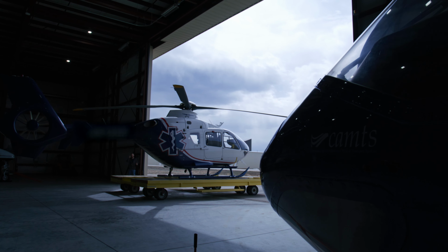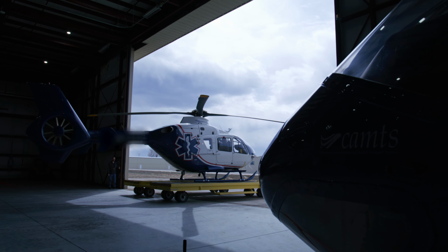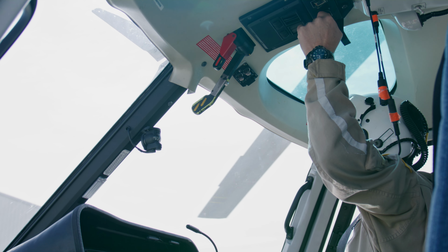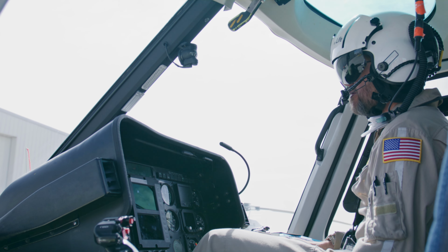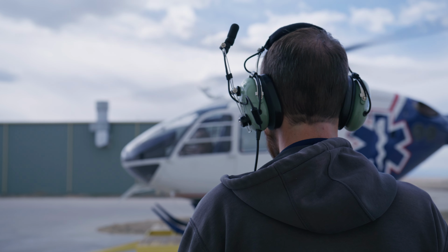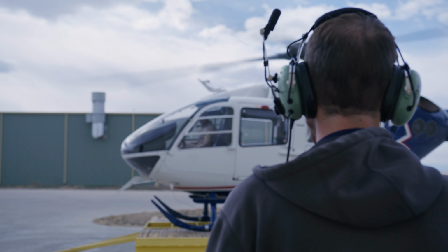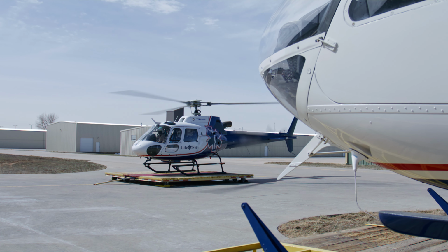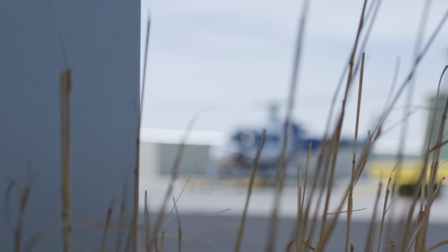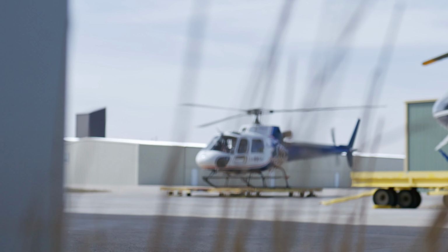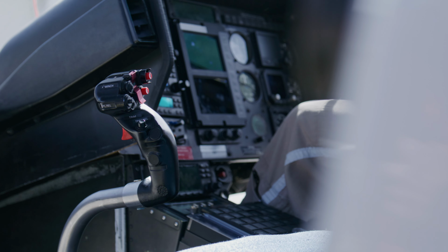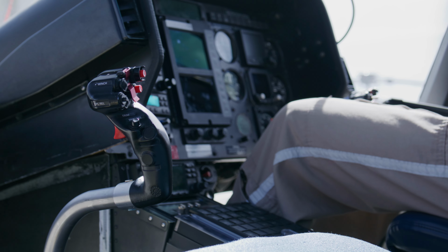The final step in the process is the drying run. This is equally as important as every other step in the task and should not be skipped or shortened. Start the engines, stabilize them at ground idle, and keep them in operation for a minimum of 5 minutes for an Arriel and 10 minutes for an Arrius. The ground run following the rinse is more than removing any water left at the bottom of the combustion chamber. Running the engine removes standing water from the bearings and recesses and brings the oil up to operating temperature, which removes the remaining moisture from the oil system.